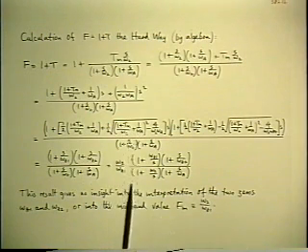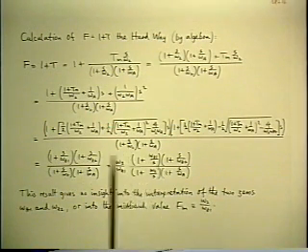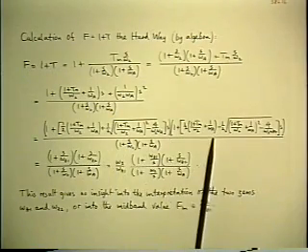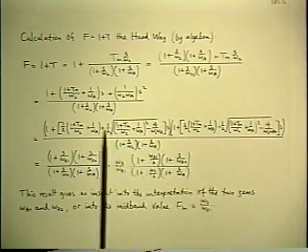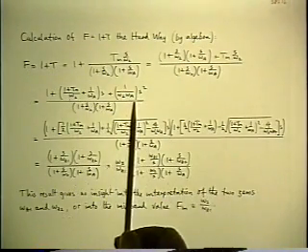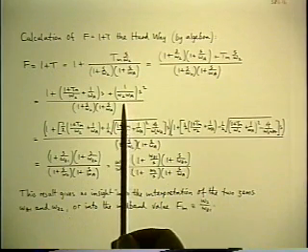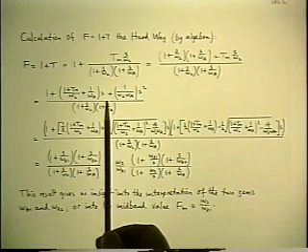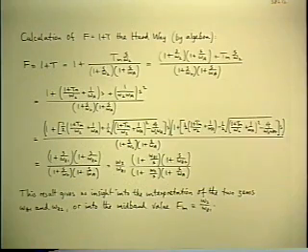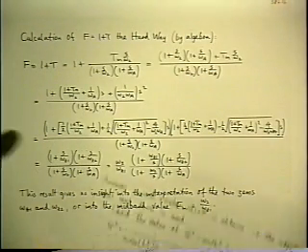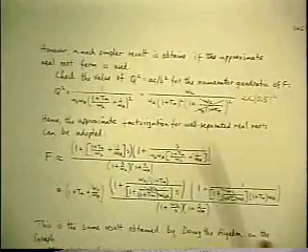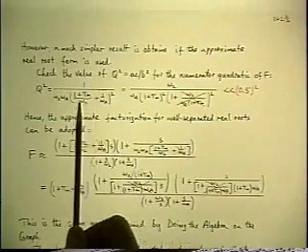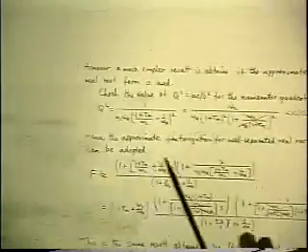Now, you can rescue this by using the suggested new version of the quadratic solution, by going back to the previous step of the quadratic and following the recommendation, which is find out right away whether the q is high or low. And if it's low, then you can factor the quadratic into two real roots with a reasonable approximation. So the first thing to do is to look at the q of that quadratic,